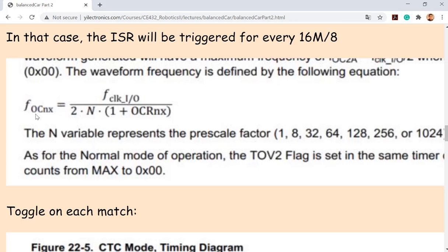Okay, so for the design here, the loop is doing the PID controllers in the loop, because you do need that position checking and adjustment to happen more frequently in the main loop. Keep calculating the PID errors. But if you compare 4 milliseconds to 20 microseconds, so 4,000 microseconds to 20 microseconds. So it's going to be interrupted pretty often. It doesn't matter because the computer can handle that.